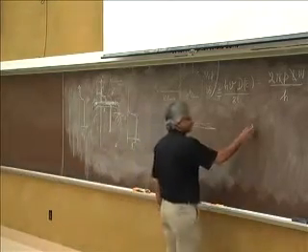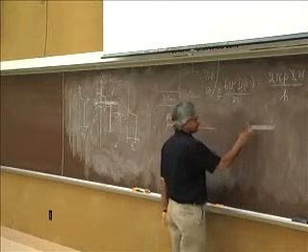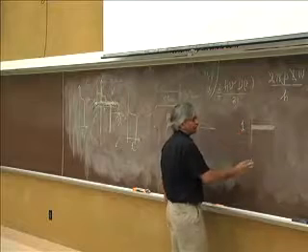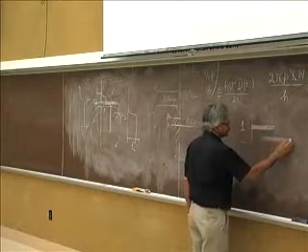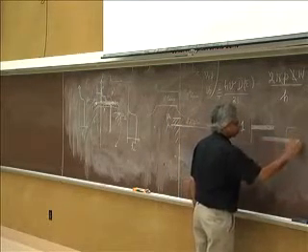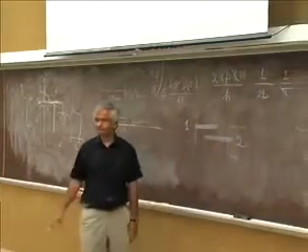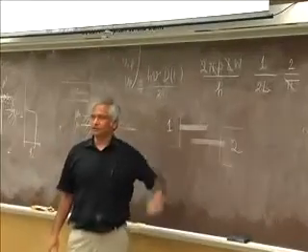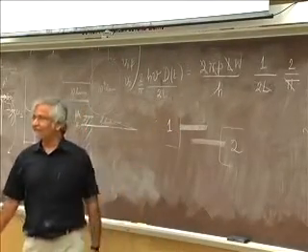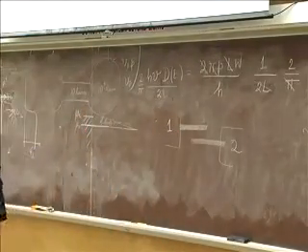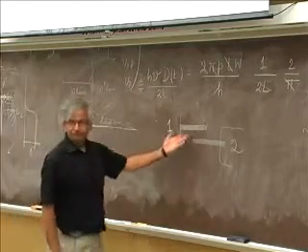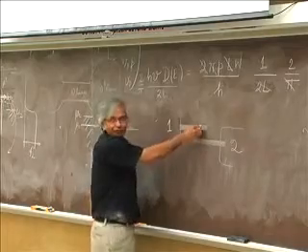Supposing you have a density of states here that is connected to one contact. This is contact 1. And you have a density of states here which is connected to 2, let's say. So one group of states connected this way, one group of states connected that way. Now, if you had an elastic resistor model, only elastic processes go on inside, no current can flow, because electrons come in here, they can't go anywhere.